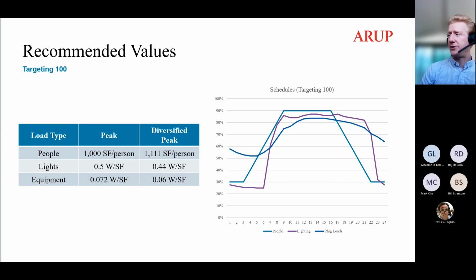The same was true for corridors and nurses stations, where in looking, we worked with designers of Kaiser's past hospitals to ensure that we understood the lighting patterns in corridors in particular. And then looking at those spaces from an energy model perspective as what if we lump these together, given that they're both a flowing volume within the hospital, but also in trying to simplify the amount of inputs that go into the energy model. What we looked at here was testing if we group these as a single zone within the model, and then look at values for people, lights, and equipment that align a little bit more with the corridors, but with a bit of a higher value on lights and equipment than may be typical.